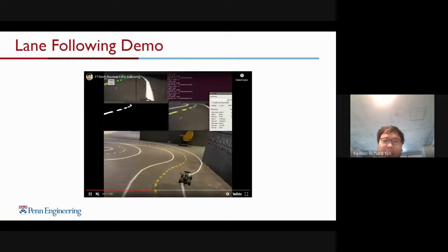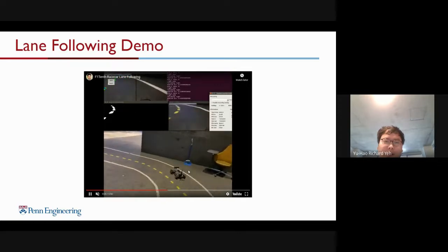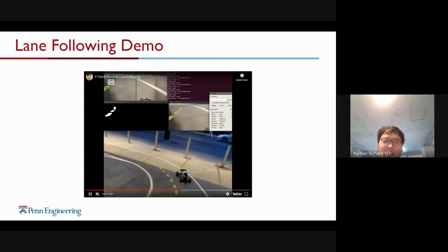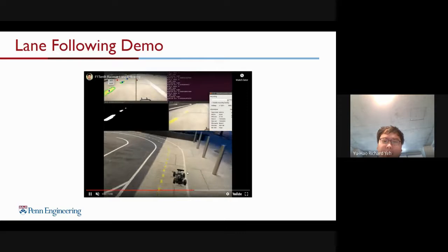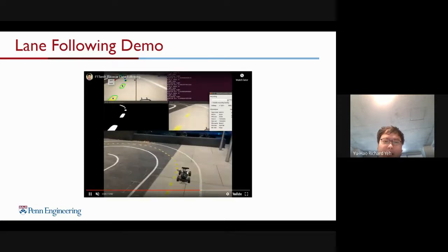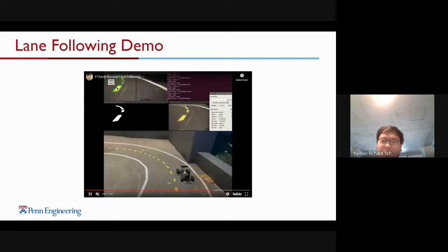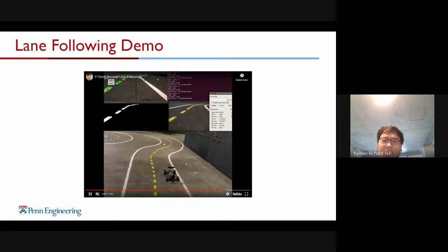The top 4 frames are recordings from the system. So the very top left frame is the lane detection node I showed earlier, with the waypoint that's following the red dot. And then the black and white image is the output from the color filters and the bitwise and.